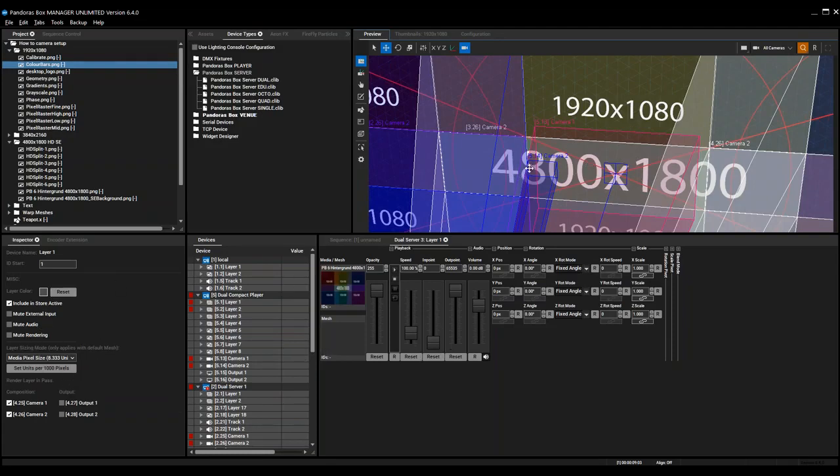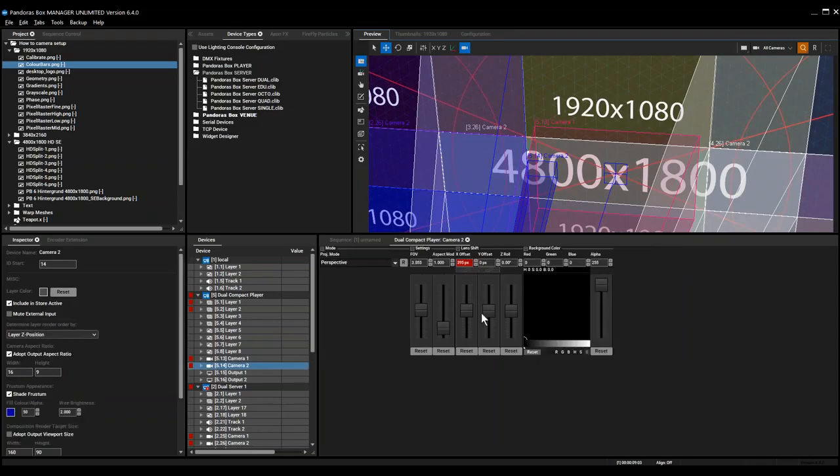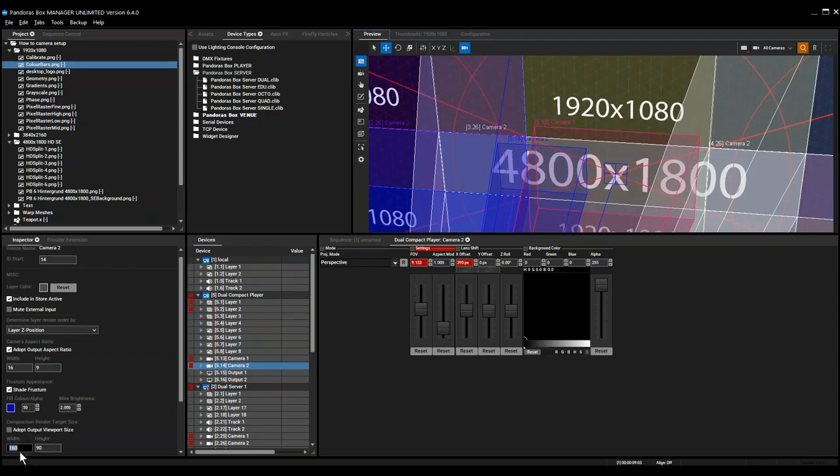And now, of course, maybe I do it for now a bit bigger. As you can see, it will auto-calc. If I use these values here, it will auto-calc my field of view and set it to the correct value, as long as I'm not having it as active. So if it's active, you can change things here and it's not doing something, right? But if you reset, it will calculate the field of view out of this value.